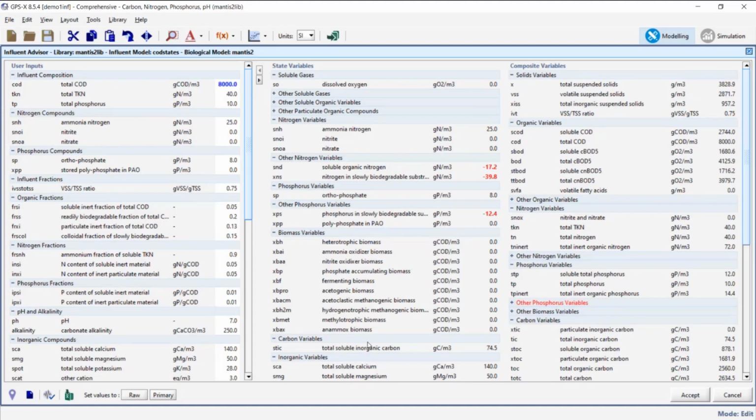this can come out negative. And so just to go back to the slides, you may remember that I said some of these fractions are things that you're going to have to change. And as part of that, one of these things that you typically have to do for very large values of influent total COD is probably set these to a lower value than you would get in a municipal plant, or potentially 0. So I'm going to set these to 0 now.